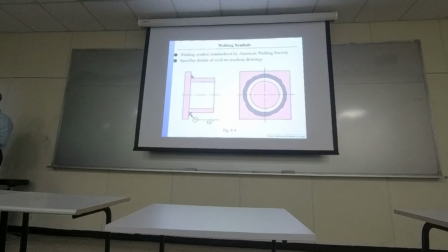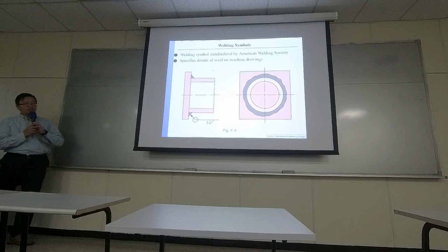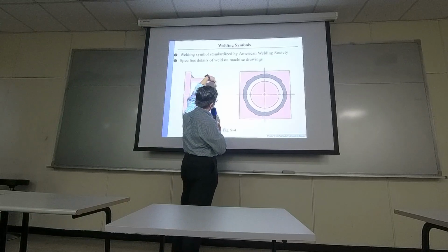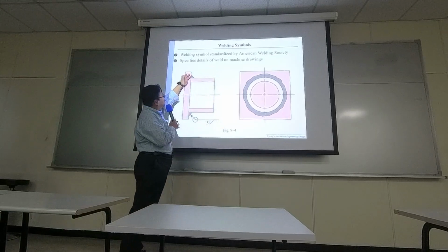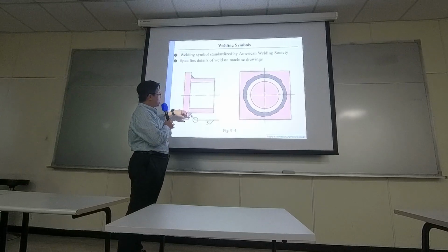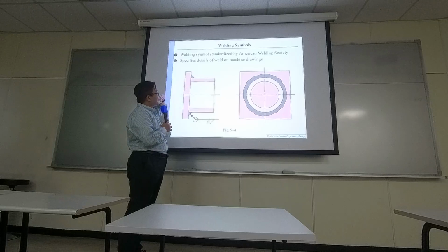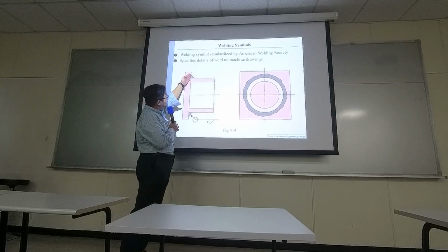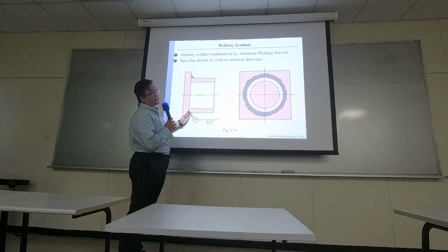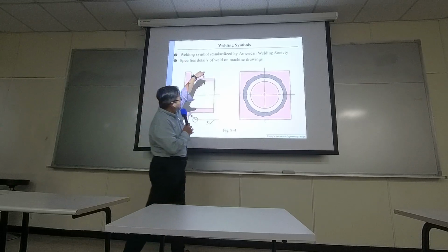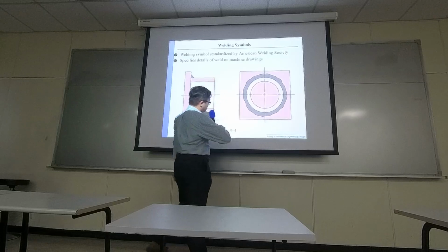So if we are focusing on this particular material, if I have one external load coming from the side going down, the welding material is going to carry the external loads, and at the interface there will be some shearing force if the external force is going down.